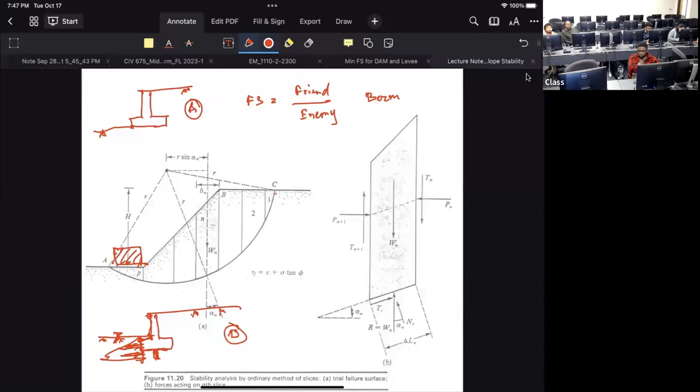The soil gives you a significant reaction like this, and that's one of the biggest advantages of using soil. In earth structures, you can use the passive resistance of the soil in your design because it always gives you the resistance, no matter what. That passive resistance comes from when you're pushing the soil.